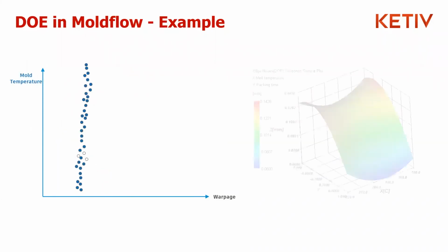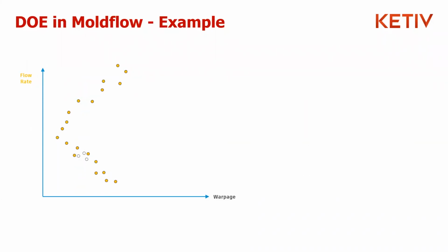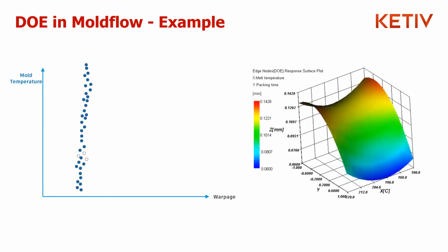It reminds me of that curve too. Reminds me of when you have two people arguing about their experiences. It quite often depends on what side of the curve they live, and nonlinear relationships like this are very hard to predict. Yeah, absolutely. Unlike the mold temperature in this case, where again, you see exactly what's happening. You see that there really isn't all that much effect that mold temperature has on warpage. Stop tweaking that knob, please.